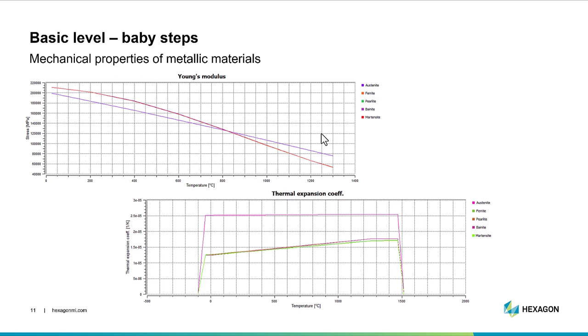And just like I mentioned, we need many different thermomechanical properties to run that kind of simulation. In this example here, we have a Young's modulus that's a function of temperature and phase fraction. The phase fraction is needed if you want to include, for example, transformation to austenite and back into whatever other phases you want to form, martensite, bainite, pearlite, and also the thermal expansion coefficient. These curves were calculated analytically, and you can validate if they are okay to use in the simulation based on experimental data that you run on a Gleeble machine.